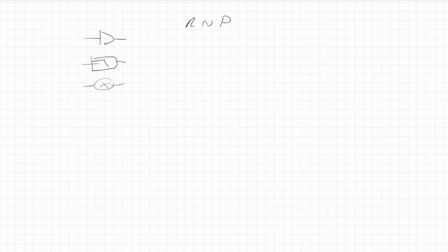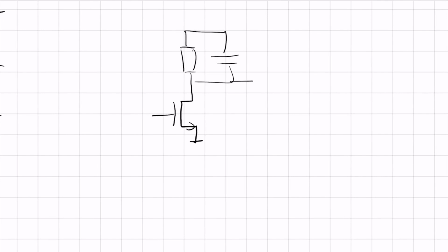And I would like to illustrate it with a simple example. I take a 1-stage amplifier, just an NMOS with a resistor, and maybe a capacitor to set some bandwidth. There's an R and a C, and this one has a W over L. And I play with the input voltage and I get inverse gain over here.